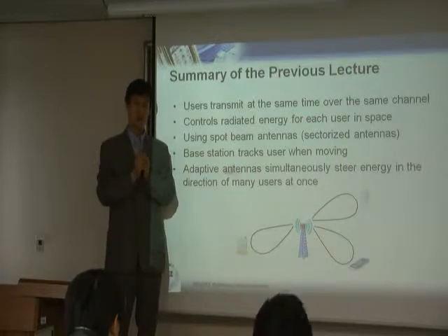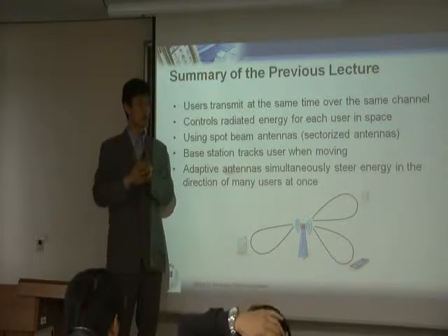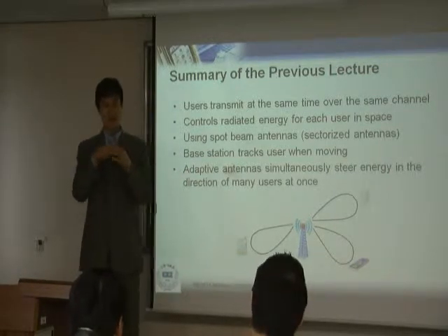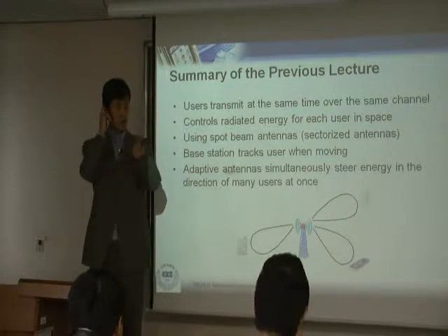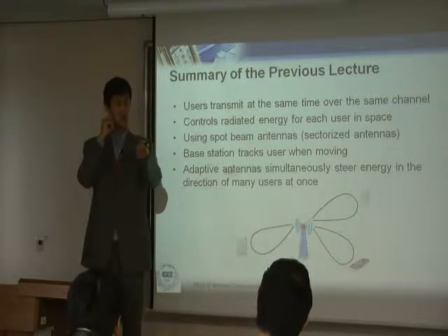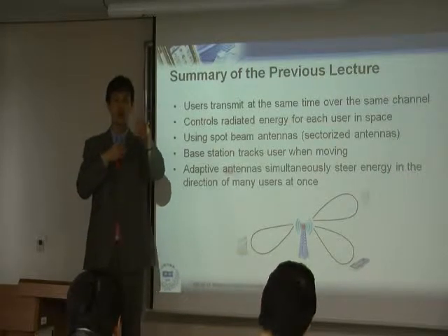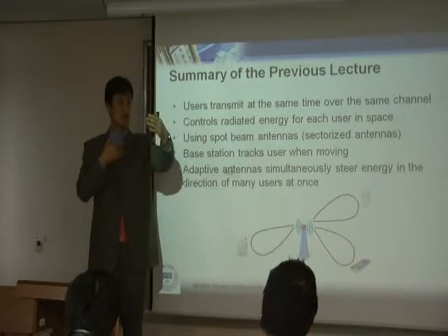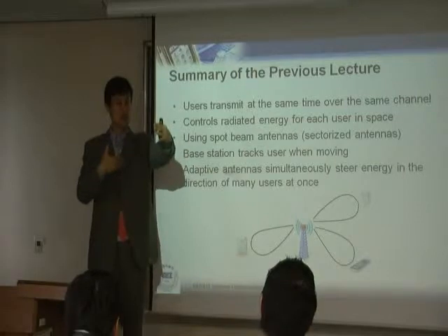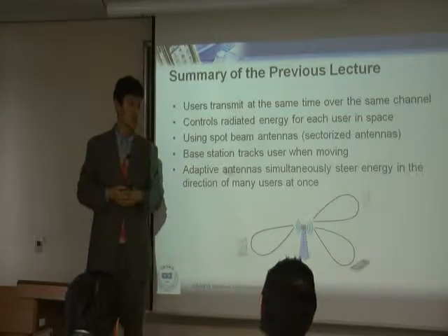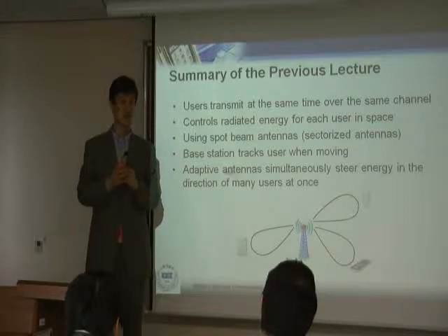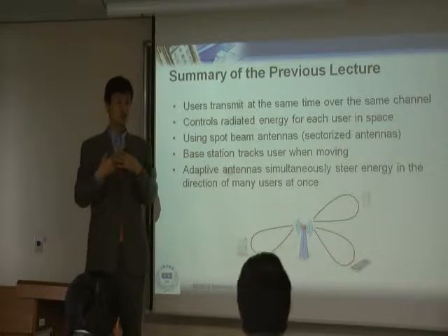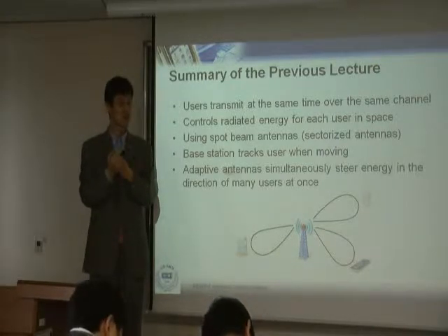But that's downlink only. Then how can you make uplink synchronization? That's the question. For uplink, you have to transmit. But in order to transmit and have the base station receive it, your time and the base station time have to be synchronized. That way you transmit and the base station understands. But what we are trying to do is uplink synchronization. So how can you do that? Without uplink synchronization, you have to transmit something.